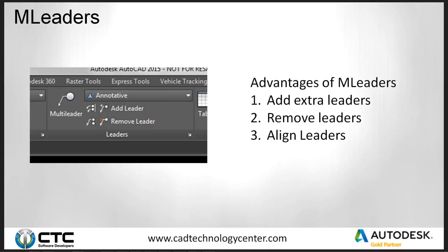MLeaders. Cool little tool. The advantage of MLeaders is the ability to add extra leaders. We might want to have one callout but have it point to 3 different objects. Well, with the old-fashioned leaders or QLeaders, you had to come in and create 3 brand new leader lines, put text on one of them, but leave the text blank on the other 2. And then you had to move it. Well, if you move the text, then you had to move all 3 leader lines.